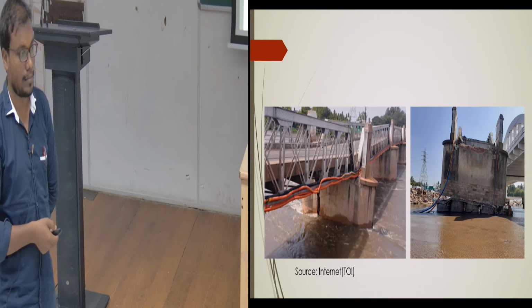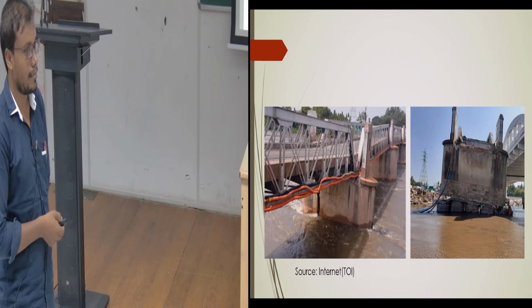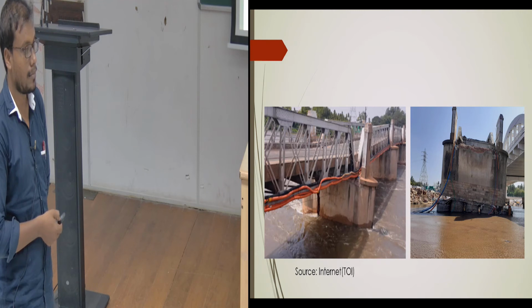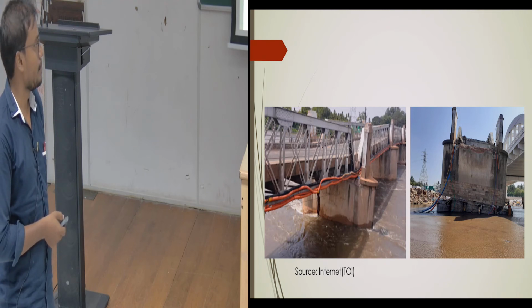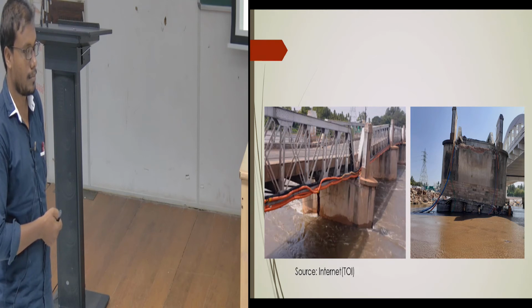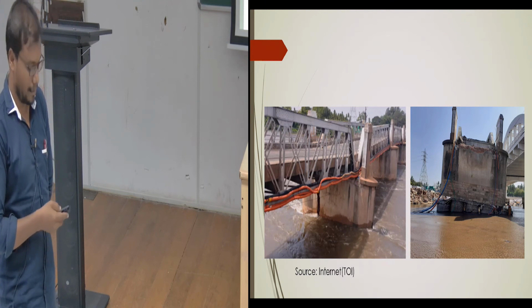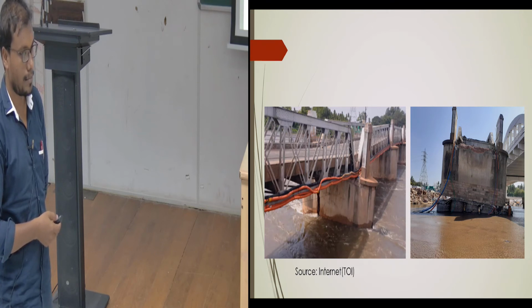It was dry, and people started taking sand from this place, river sand, and thereby it caused some settlement. That was another big issue, the cause of this problem. So ultimately this pier got cracked. It cracked earlier, but further after doing it, due to its sulfate, it started widening, and at last, when it reached its ultimate stage, it failed.